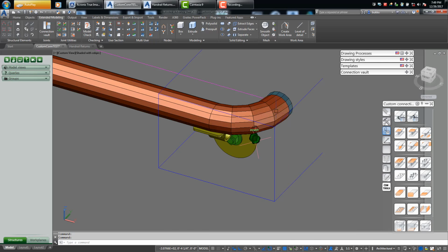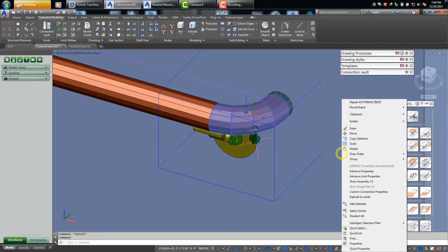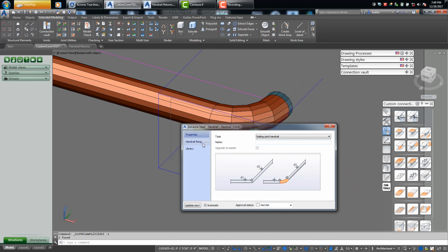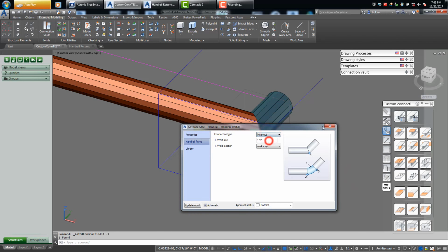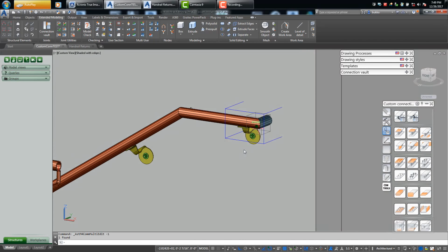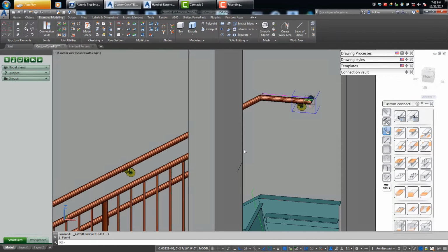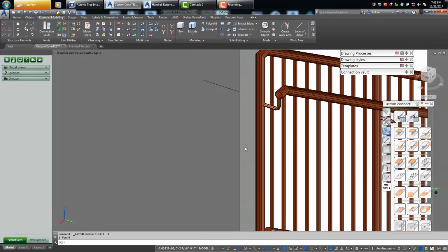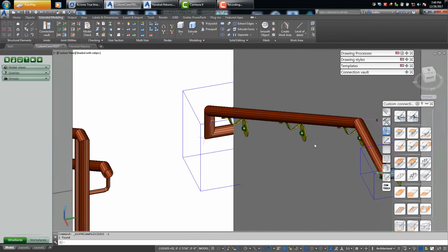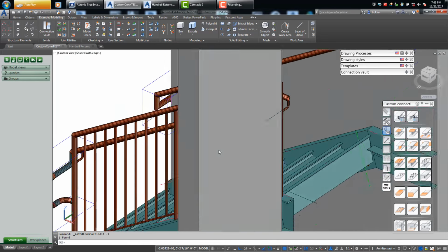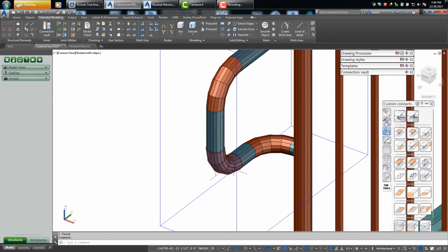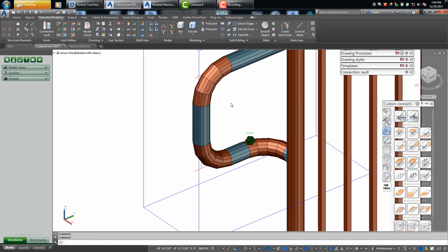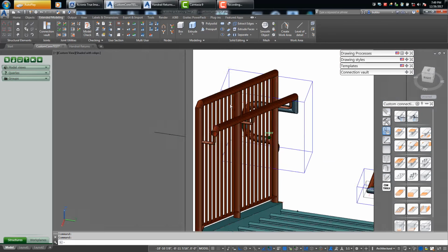I gotta get it, hold on a second here. And again, real simple to do. You've got your mitered point, or your return that's an elbow or curved. I set these at 3-inch centerline radius when I'm dealing with the elbows, because that's what our bending machine bends to 1 1/4 pipe at.